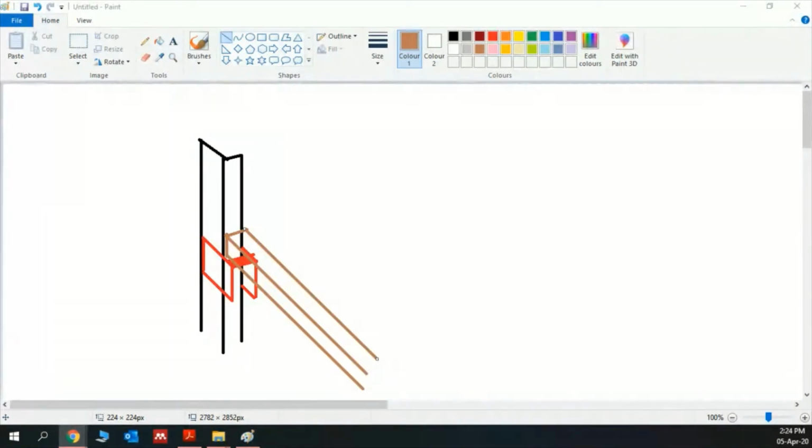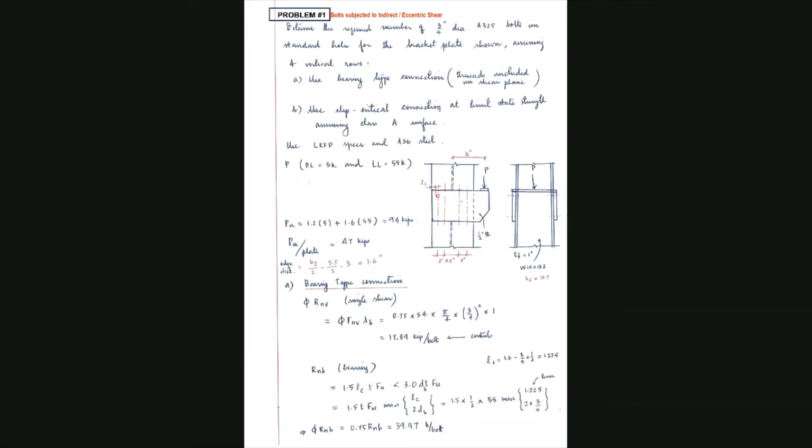The edge distance, I don't quite get it. Yeah, we'll go there now. Doctor, always we will use plates to connect columns and beams? You use this type of connection, a welded connection. This is how we connect probably some beam to this one. You need a connection. This is just one example. It need not necessarily be a plate. You can use an angle. One angle is connected to probably the flange of the column, and the other leg is like a cantilever, and you can support another member on that. This is an example. You get the idea? It could be anything else.